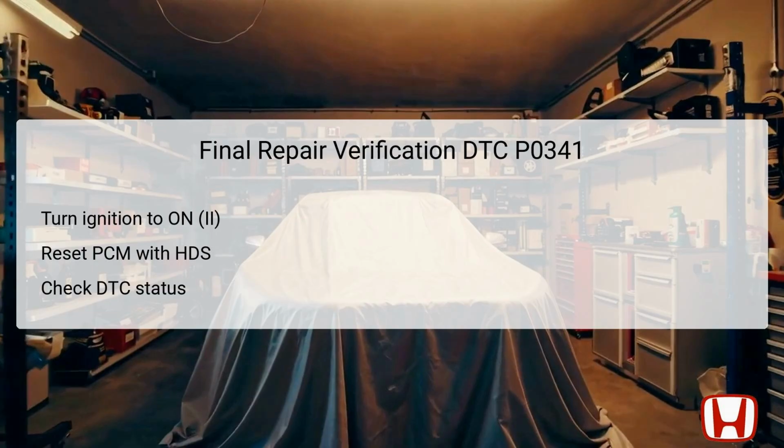Once all troubleshooting steps have been completed, it is crucial to perform a final repair verification to ensure that the DTC P0341 has been resolved. Start by turning the ignition switch to the on position. Utilize the HDS to reset the PCM once more before proceeding to do the PCM idle learn procedure to calibrate the engine's idle behavior effectively. Following this, complete the CKP pattern clear and CKP pattern learn procedures to synchronize the crankshaft readings correctly.